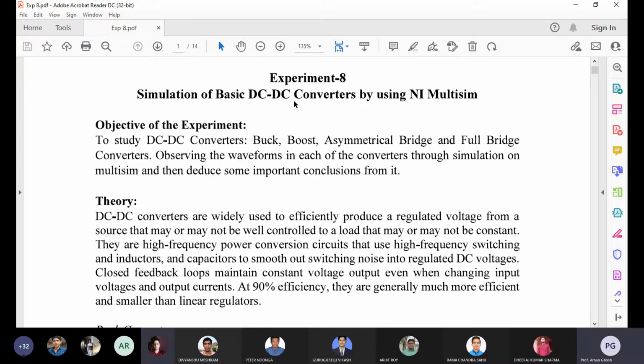So we can also use that reverse polarity based converter, that is SEPIC converter. These are examples of non-isolated type DC-DC converters. We also have isolated type DC-DC converters like forward converter, flyback converter, push-pull converter, half bridge converter and full bridge converter.